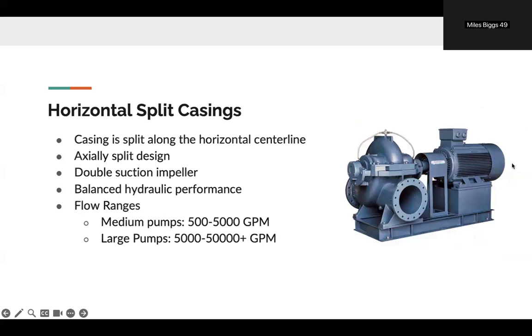Horizontal split casings. So this is going to be a casing that's split along the horizontal center line, and it's an axial split design, and it has a double suction impeller.